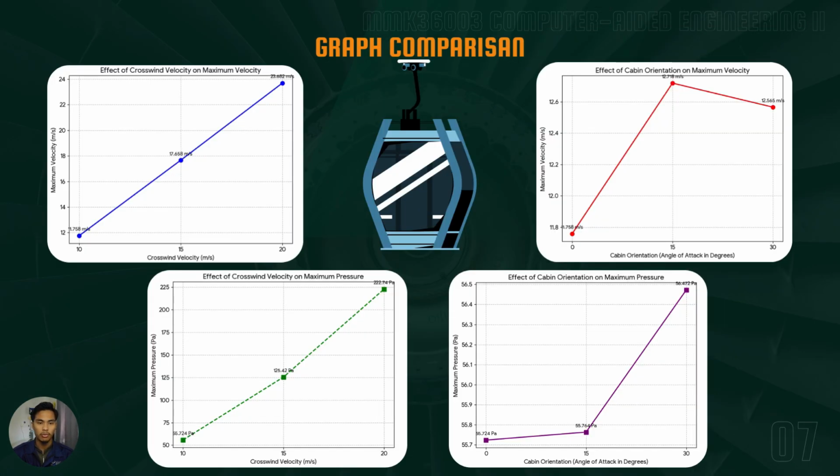Then we will go to the graph comparisons. This is my graph comparison for each independent factor. From here, the comprehensive analysis confirms that crosswind velocity is the primary driver for structural loading, while orientation dictates local flow stability. A doubling of wind speed leads to a linear increase in airflow velocity, but results in a fourfold exponential surge in pressure loads. Conversely, changing the cabin angle has a negligible effect on total pressure magnitudes, but creates a critical peak in local flow acceleration at 15 degrees.